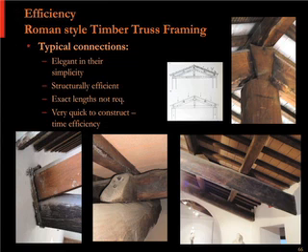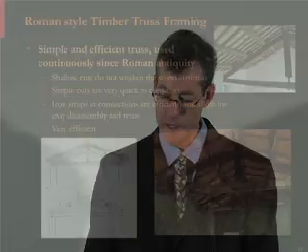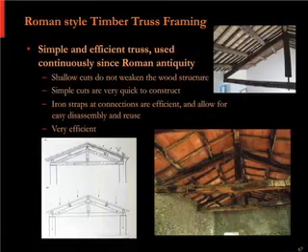And there's really no shame in using a few spikes or nails. So they did that to keep those members from sliding downhill. So that's a connection in the center that just keeps those girts from sliding down. Everything is very simple. The only thing that's even more than just a blunt cut is at the top right, that kind of keystone connection at the top of this truss.